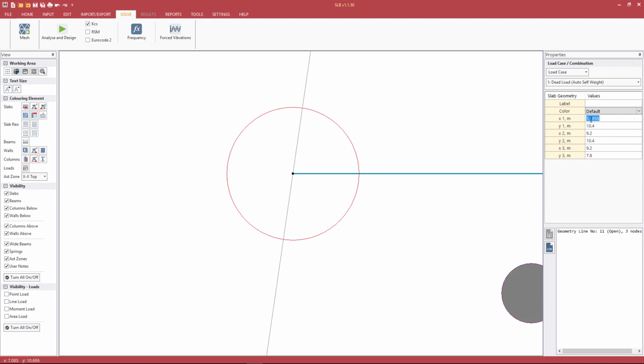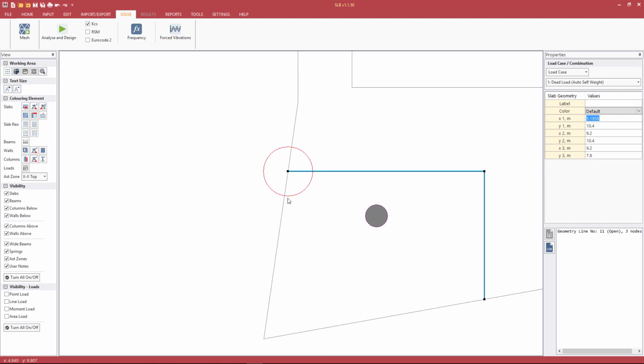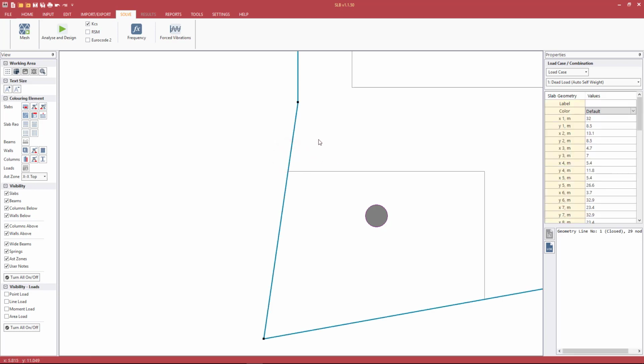However, we've introduced a high degree of accuracy into the model again, which we may not necessarily want. If we choose to keep it like this, we just have to keep in the back of our mind that if we were to round off again, we would lose this information. Now, we don't want to have to repeat work, we don't want to have to fix this area again, so probably an easier option would be to insert a node on this perimeter line.